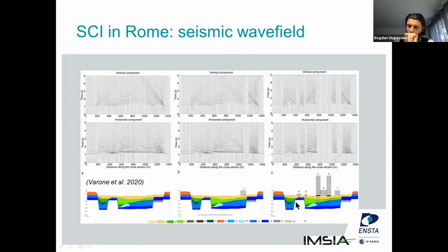We have surface wave generation at the basin edges, but we also have surface wave generation due to the lateral heterogeneities between this free surface area and this area where the stiffness or the mass are different due to the presence of the building. So in fact, we have three effects: kinematic effect, inertial effect, and surface waves in interaction with the surface wave generation process.